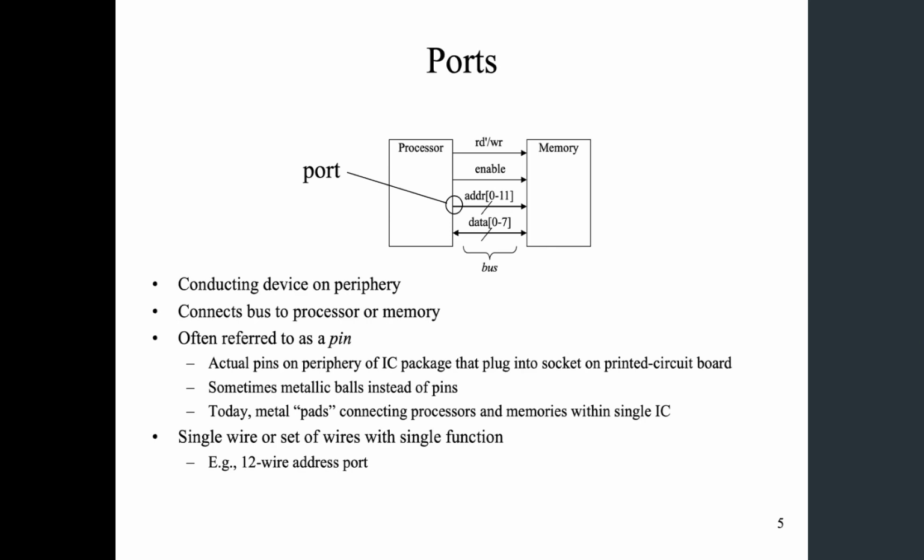We often refer to these ports as pins, and the actual pins on the periphery of the IC package can be plugged into a socket or soldered into a PCB, printed circuit board. And sometimes, physically, they are not pins, they are metallic balls. So these can also be soldered into a PCB.